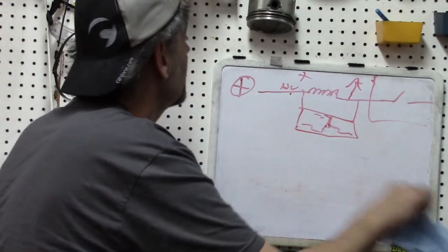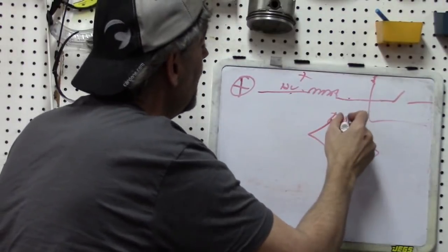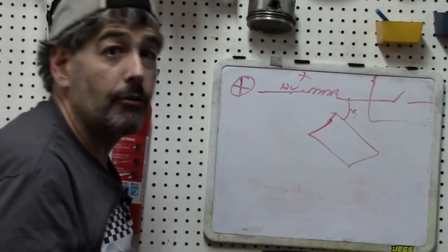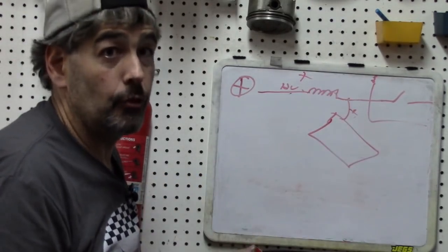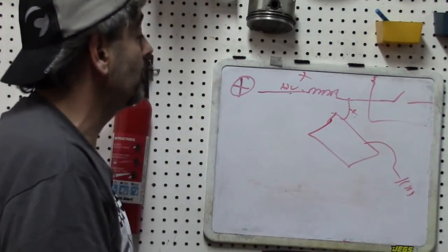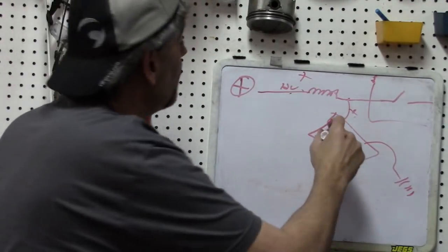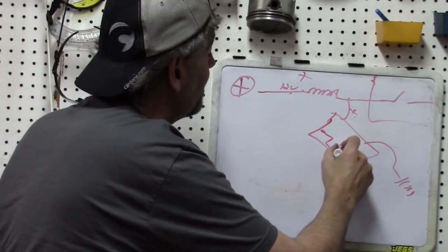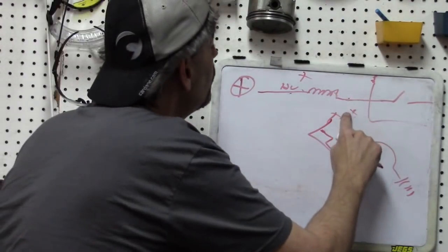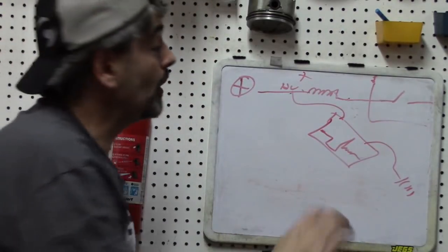And as a matter of fact, the way I'm going to prove this is we're going to show our usual thing, but then I'm going to connect the positive of the scope to the ground. Now, of course, that's still positive with the switch open, you know, your basic electrical. This I'm going to put to a chassis ground, okay? And we're going to see, of course, it'll be inverted now, but we're going to be able to pull up that same exact thing on this side of the circuit.